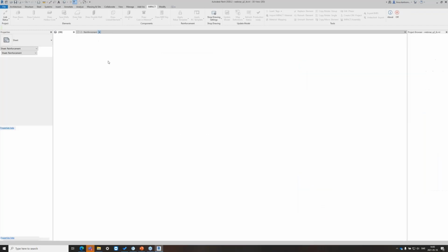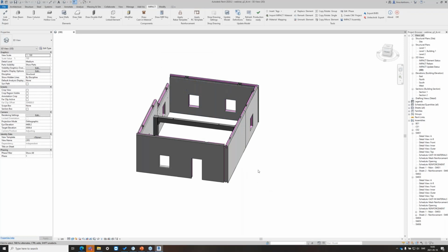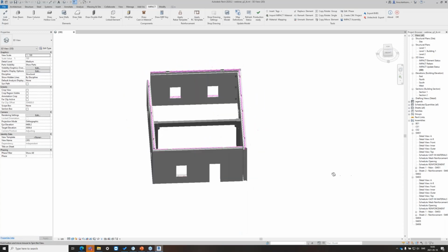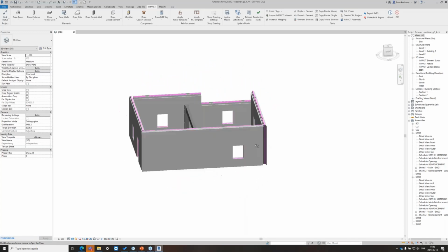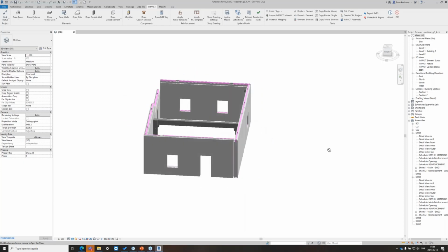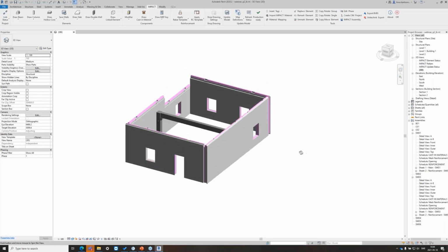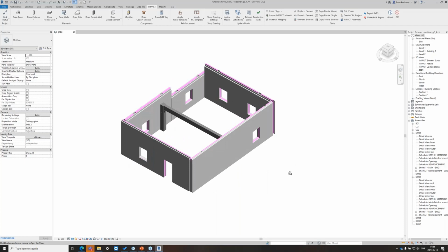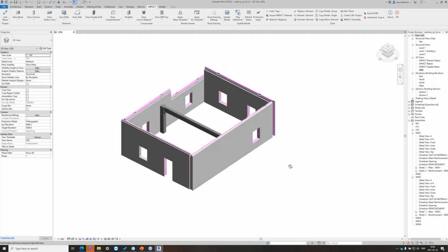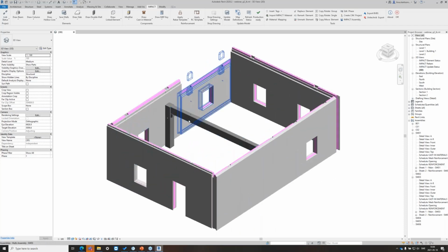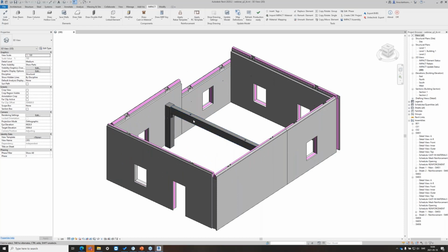I think time is running, but in the end I can probably just draw a basic solid wall, and you can see the result. But before we do that, I want to show you the shop drawings for columns and beams as well. It's pretty much the same deal, so we won't go into the settings for these ones, but we'll just generate shop drawings and take a look at the result. Because as you know, I said that we were having a new feature called the protruding rebars.